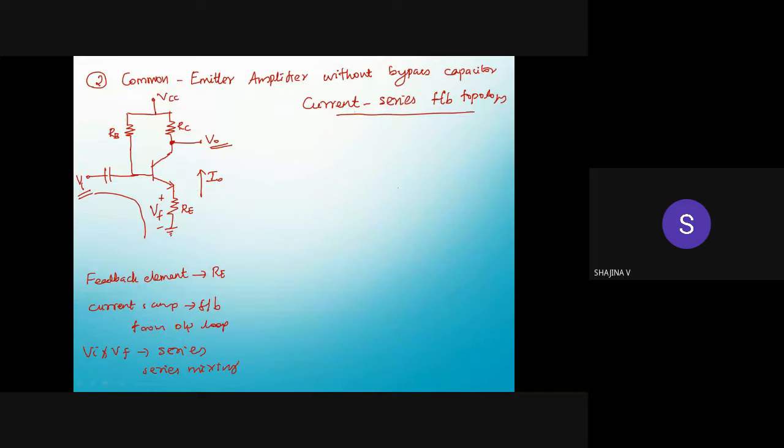That is, first of all, you have to find the gain without feedback. So the gain of this amplifier part without feedback. So you have to find A. What is A? Actually, we are not taking output voltage, we are taking the output current, that is I naught, divided by our V in. So I naught divided by Vi. I have to consider this is actually not Vi, Vs. This is the source voltage Vs.